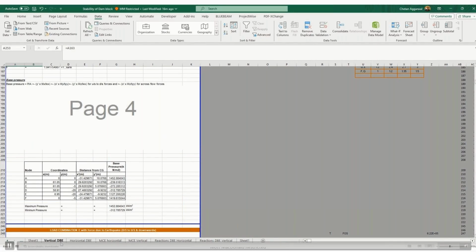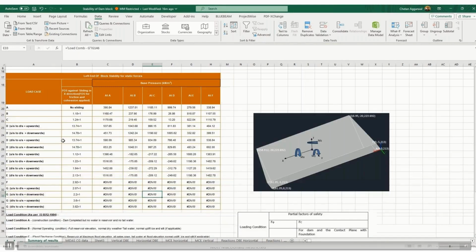Let's see the summary, where is that? But we were getting some negative pressures also, and let's see in E condition. So 1.22 we are getting. Okay, so this is also a bit, anyway, for 1.12 also. So this is quite close to 1. But it is more than 1. So from pseudostatic analysis, our dam is safe.